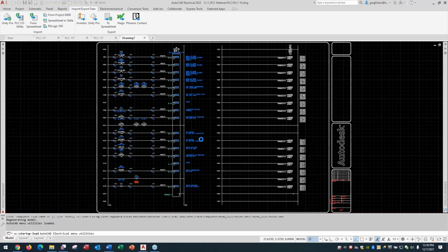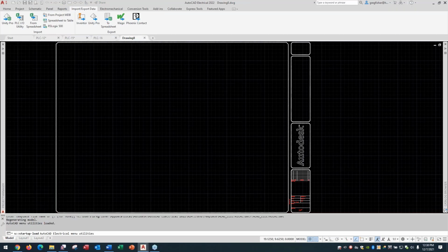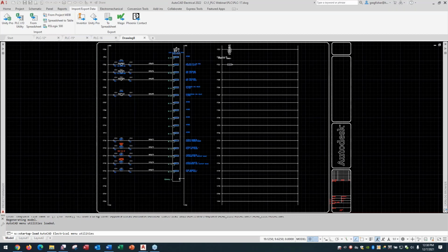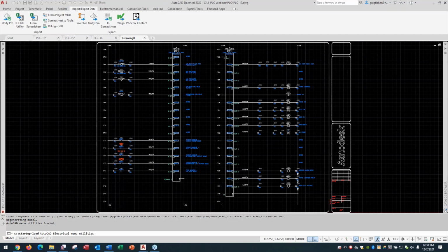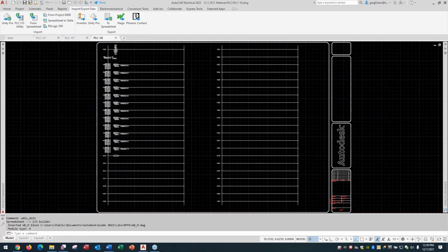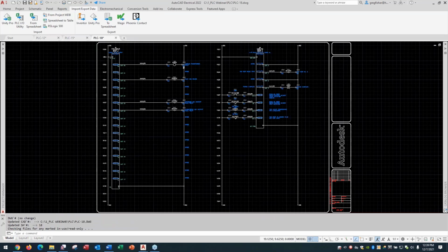And that's what I talked about. It's trial and error. To nail it down exactly the way you want, you're going to have to run it a couple of times. And I would start small. Get your setup first, meaning start with one drawing. One drawing with everything in it will get your setup in here as far as distances between components, the input module placement from the neutral. Start with one drawing. Start with a couple of modules. Get the setup from the utility done first, then just add to the spreadsheet all the information from there.